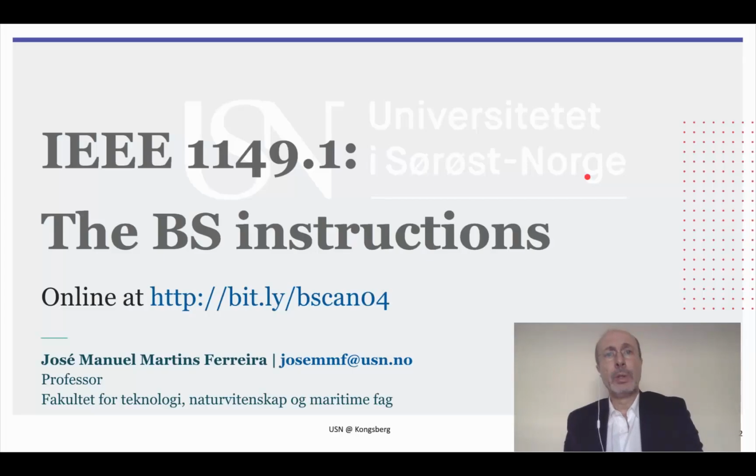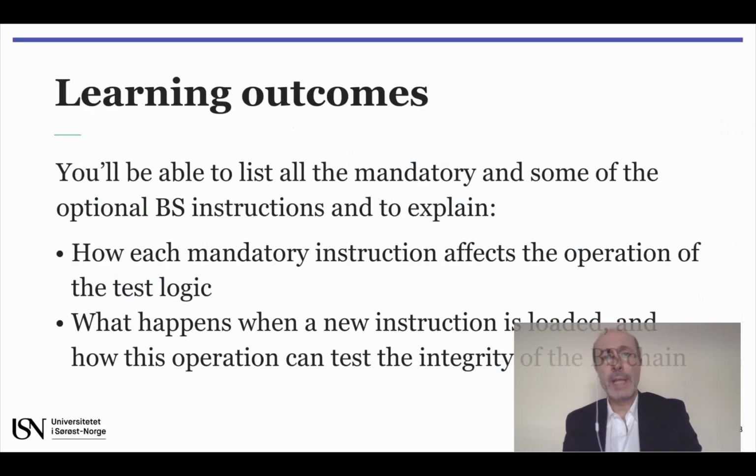In this presentation, we will look into the most common boundary scan instructions. At the end, you should be able to list the most important instructions, to explain how each instruction affects the operation of the boundary scan infrastructure, and also how the process of loading a new instruction can be used to test the integrity of the boundary scan chain. Or in other words, to check if there are any faults in the TDO, TDI, TMS, and TCK interconnections.